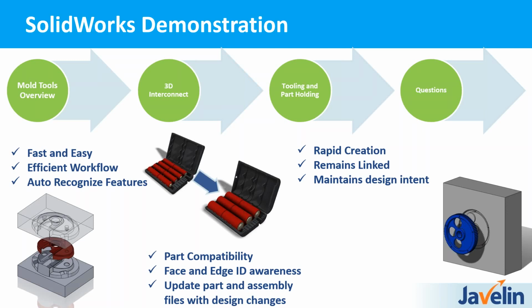Is it mandatory to use 3D Interconnect with mold tools, and can someone survive without it? It is absolutely not mandatory to use 3D Interconnect. You can run through a regular import process, or you can just open the part using 3D Interconnect, which makes it faster to open parts.